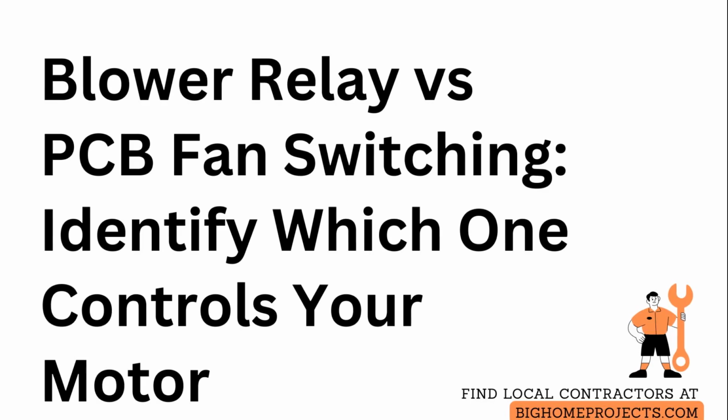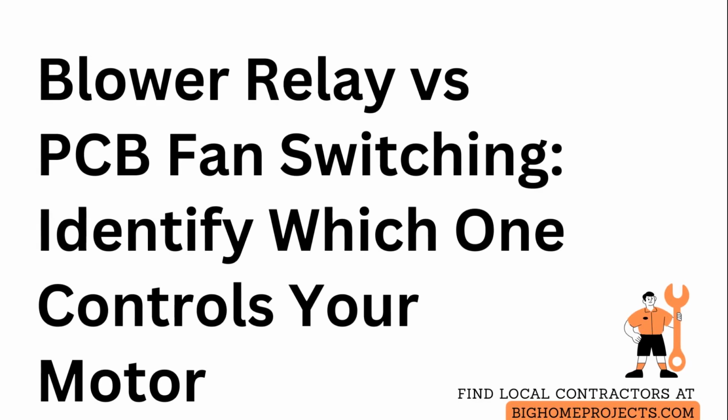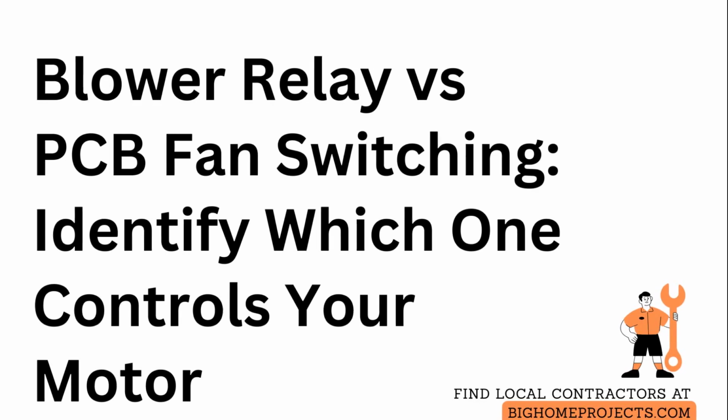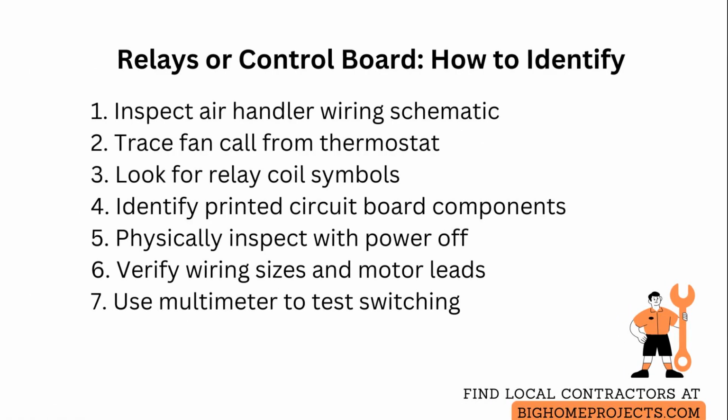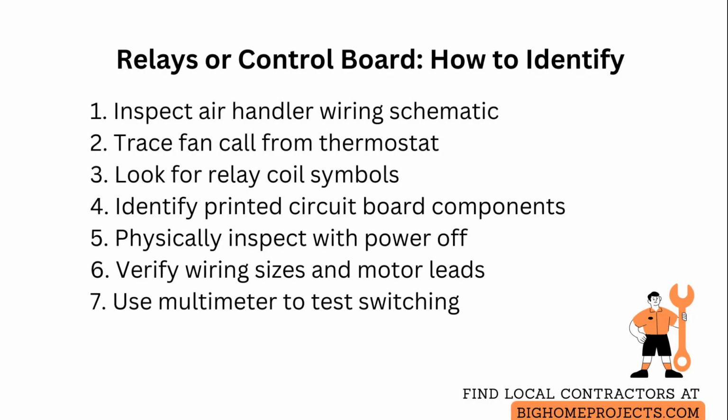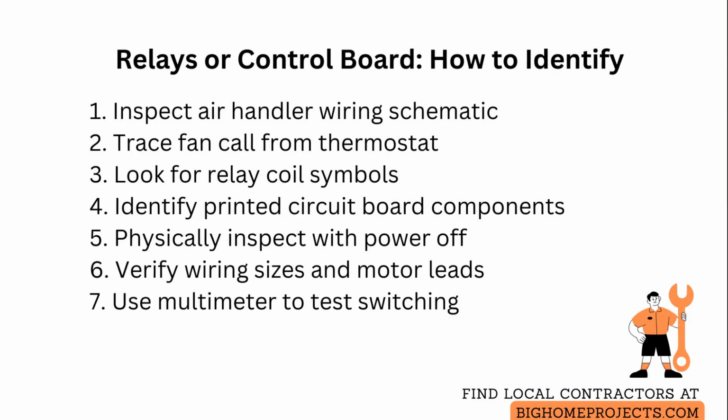Does my heating, ventilation, and air conditioning system use relays or a control board to switch the blower fan? Look at the air handler wiring schematic first, because that diagram is the quickest, definitive answer. Find the blower motor connections and trace the fan call input from the thermostat or control transformer.